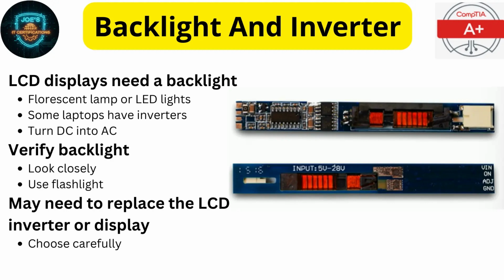These are very common on laptop computers, and you may find these inverters in the bezel of the display itself. You can check with the manufacturer of that laptop to see what style of backlight is in use, and if it is a fluorescent light, you can also check to see where those inverters might be and what the process might be to swap those out for a new one.